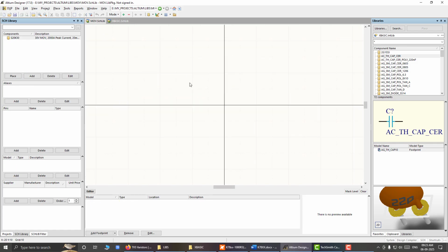So let us go to our own library and start the drawing. Let us first place, and also please take care about this origin. This is the origin where the x and y axis meet. So draw around this only, it is better to draw around this. Either put the corner of a pin here or the center here.